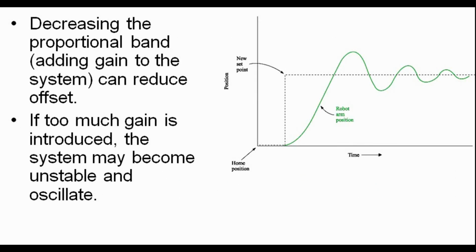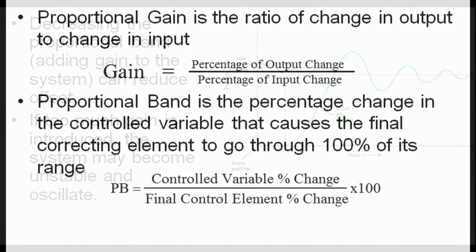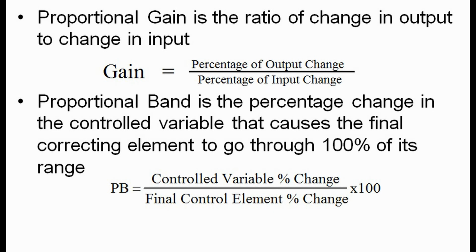Because we are using op amps in measurement and also to drive control circuits, we can change the gain to make the system operate faster or slower. The result of using too much gain is that the system will overshoot the set point and begin to oscillate until eventually it will find the set point. Of course, the result of using not enough gain is that the system might not ever reach the set point and operate very slowly.